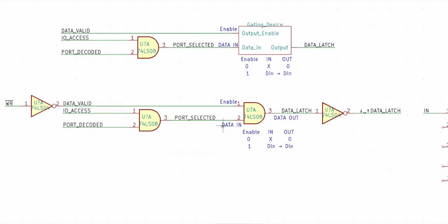Now this output is the real board signal, not just the functional signal I used in the description. And as a reminder that the transition is actually important, I'm going to put a little waveform on this label name showing what I already figured out once, so I don't have to figure it out again, that this is going to have a strobe with the rising latch on the trailing edge.